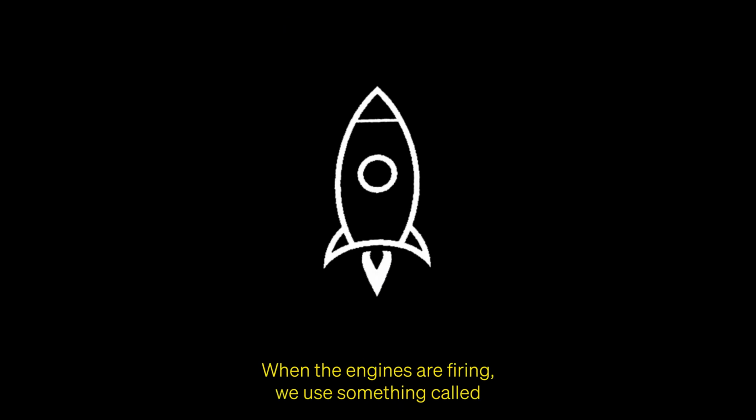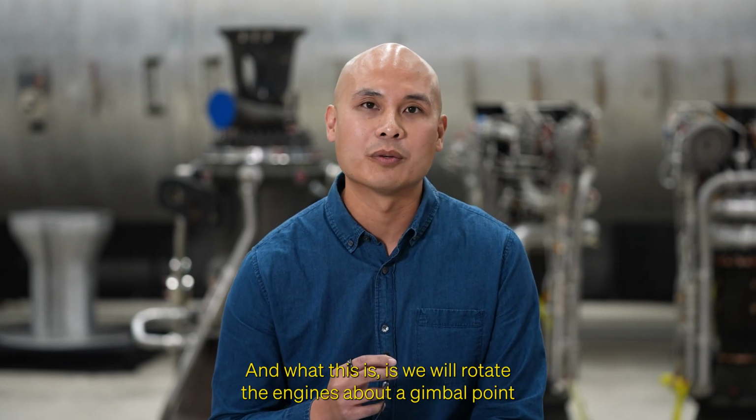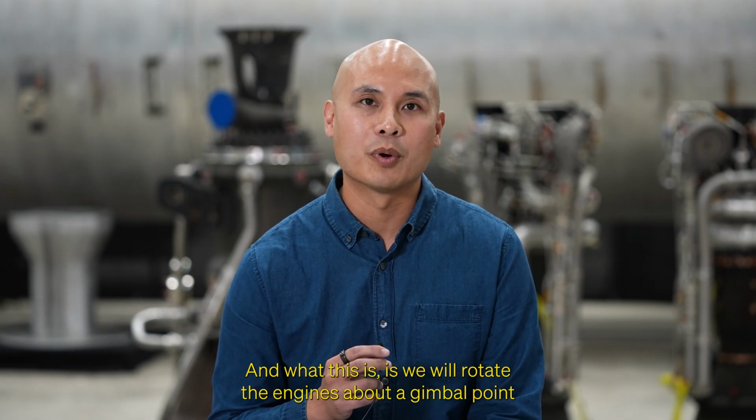When the engines are firing, we use something called thrust vector control or TVC control. And what this is, we will rotate the engines about a gimbal point in order to use the thrust of the engine to create a torque about the rocket, and we can use this to actually turn it to steer it into the direction that we want it to go.